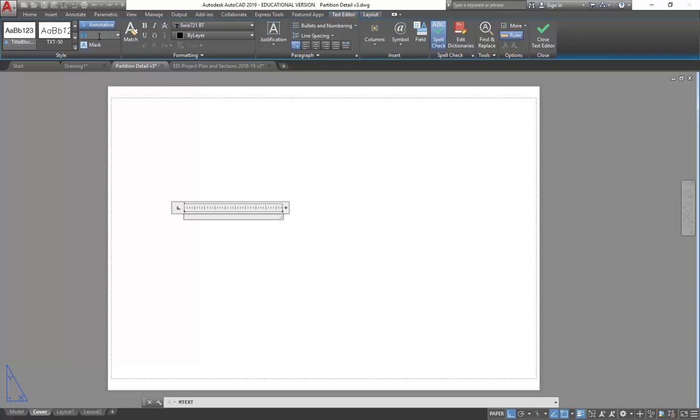And so what you end up doing is just making sure that you've got a good middle value here. So 3.5, that's fine to start with. And what you don't want is those big values. When you see values like 300, 500, that's set up for model space, and you've got to just keep an eye on that. So as long as you know that it's paper units, and actually, do you remember how to check that it's using those paper units? The thing above. So see how it's got the annotative highlighted? Yeah. So if you notice that isn't highlighted, that's where you might have some problems. So again, just check those things as you make your text, and it should work pretty well.